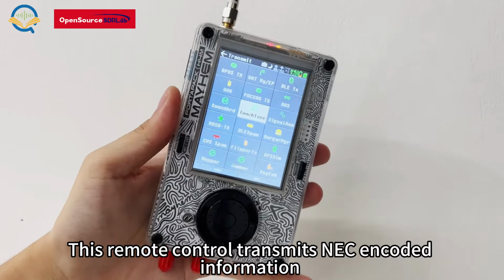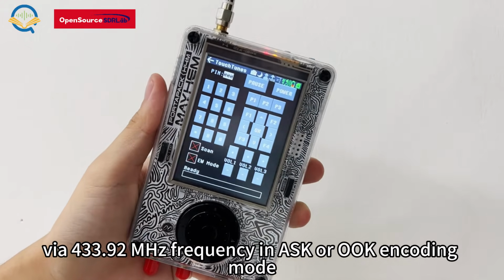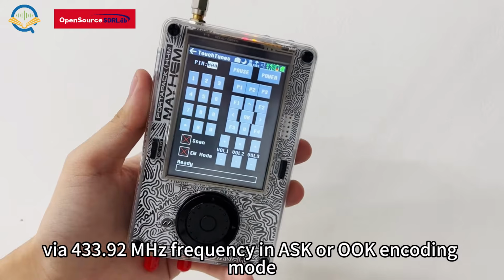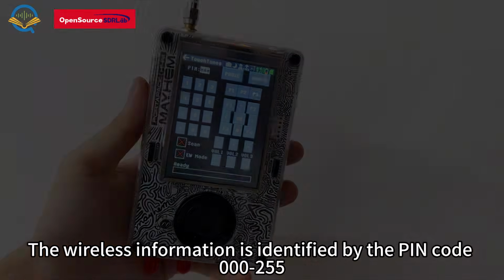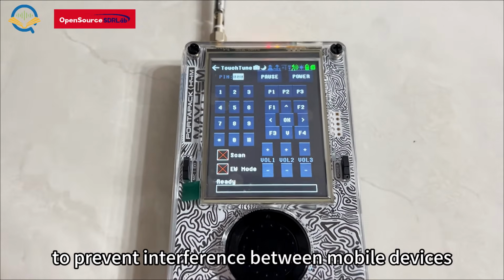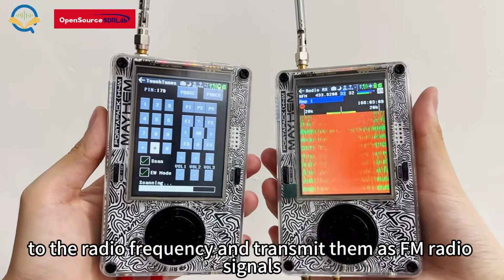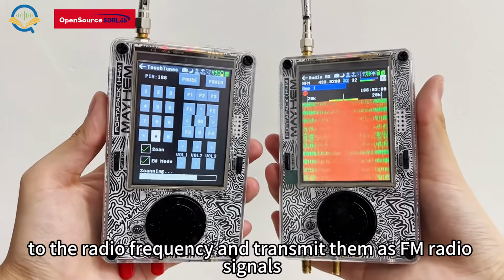This remote control transmits NEC encoded information via 433.92 MHz frequency in ASK or OOK encoding mode. The wireless information is identified by the PIN code 000255 to prevent interference between mobile devices. The TouchTune application can modulate audio files on the SD card to the radio frequency and transmit them as FM radio signals.